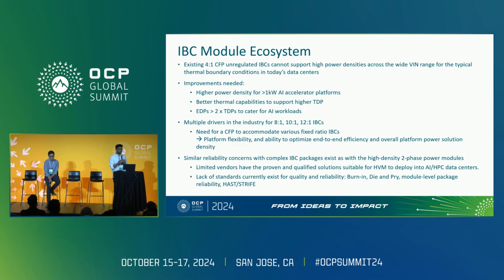And with the IBCs, as these are power modules with multiple PCBs sandwiched, with multiple components such as FETs, gate drivers, DrMOS, magnetics, transformers, capacitors, and controllers, everything integrated into these packages, the module package reliability, solder joint integrity, and board-level reliability are at even greater risk than with the two-phase power modules. So all the challenges that I highlighted before about stricter burn-in requirements and stricter production test coverage are even more critical for the IBCs.